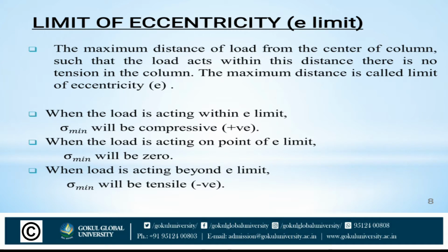Limit of eccentricity, e limit. It is the maximum distance of the load from the center of the column such that, when the load acts within this distance, there is no tension in the column. The maximum distance is called the limit of eccentricity.